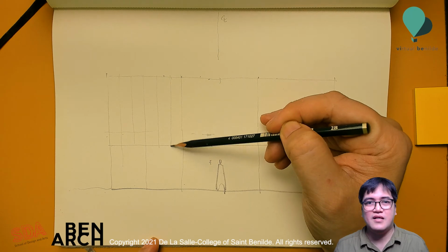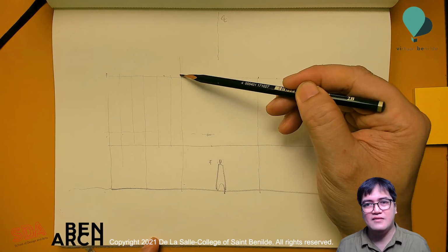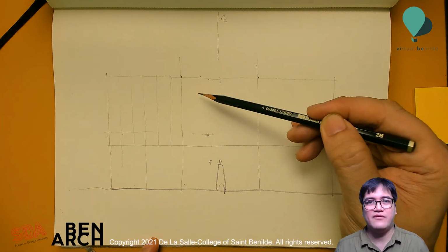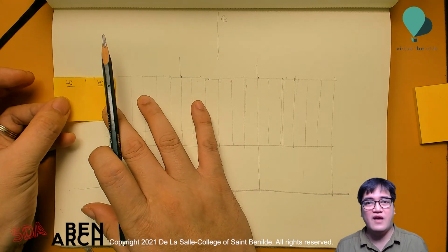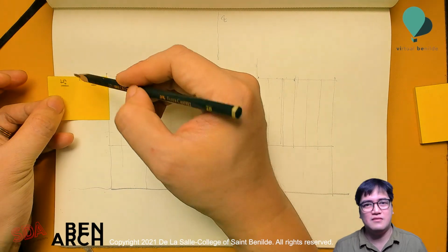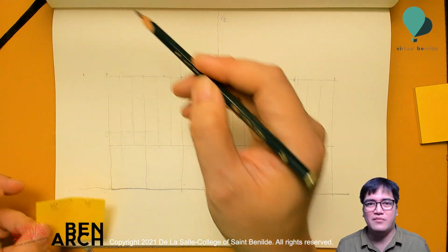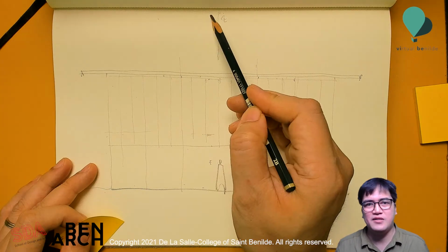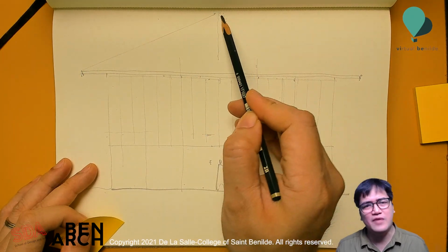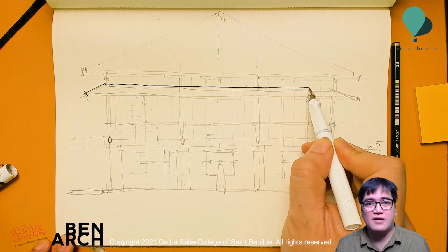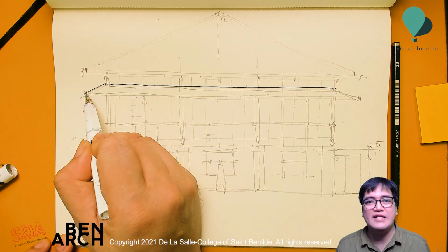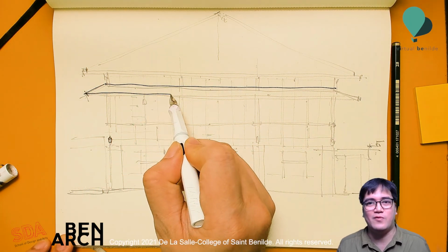Here, there is a distinct 3-bay facade with each bay further subdivided into 6 segments. Step 4, if you have roof eaves, they would be 1 meter from the walls, and the pitch of the angle of this roof is roughly about 30 degrees. Step 5, now you can start drawing the ink lines or details once you are sure about where things are.